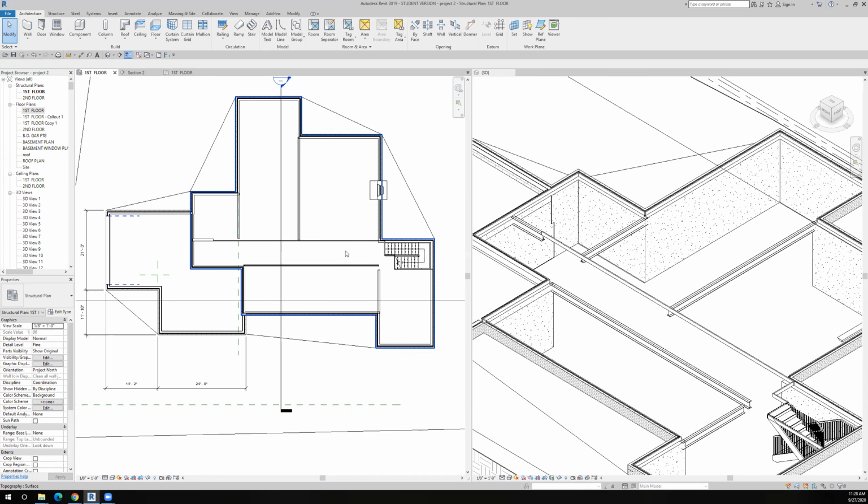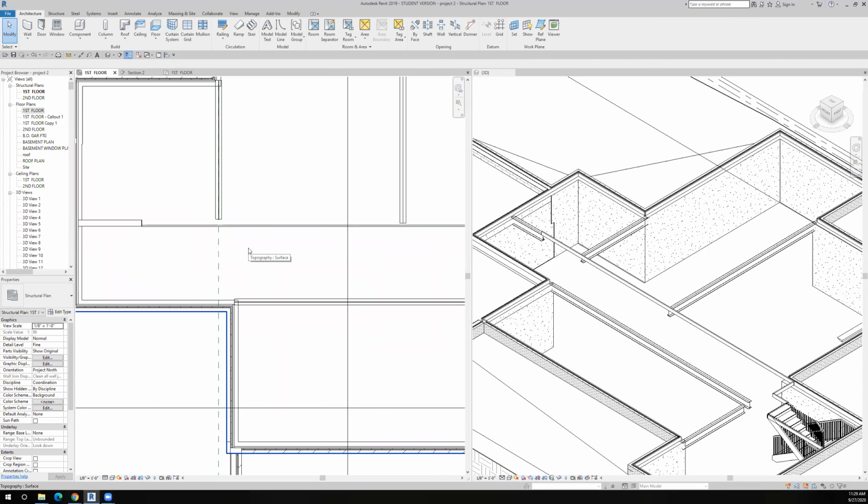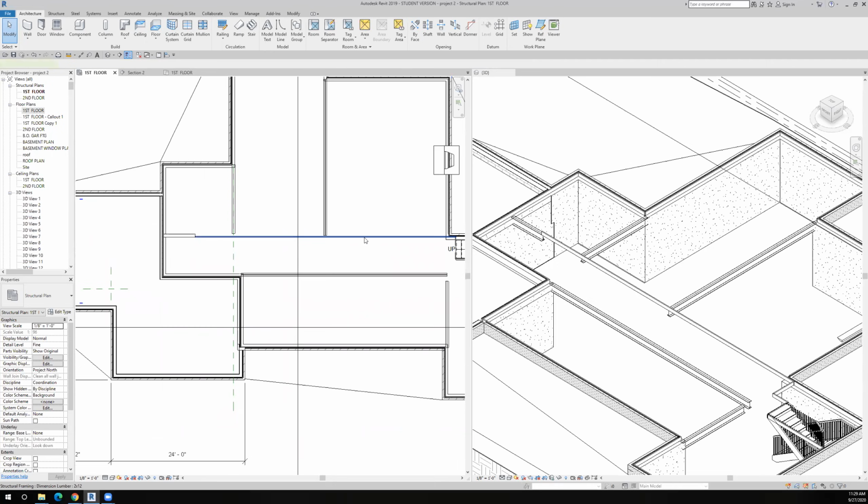If I'm going to put in oak flooring, we need to put that flooring perpendicular to the span of the floor joist. And if I have a different span of the floor joist, then I have to change the direction of the oak flooring. And I wouldn't want to change that. I want to keep it all the same. And I know my oak flooring is probably going to be around here, so all my floor joists will be the same.